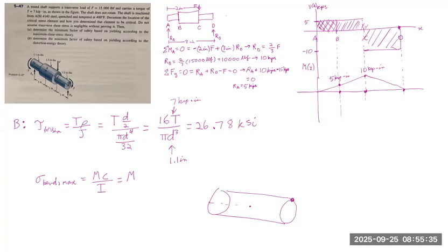Because at the neutral axis, for instance, there is no bending stress. So when you bend the beam upwards like this, a stress element located at the neutral axis doesn't experience a normal stress, but one at the top will. A stress element here will be, for instance, in tension, while the ones over here will be compressed, because you're bending it inwards, and over here it's flared outwards.